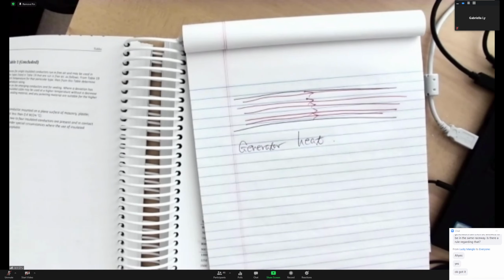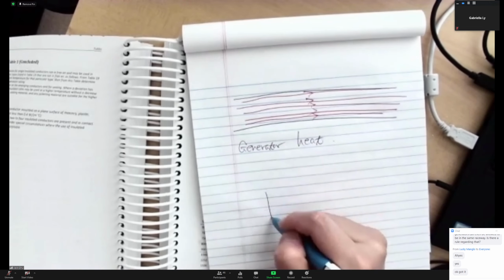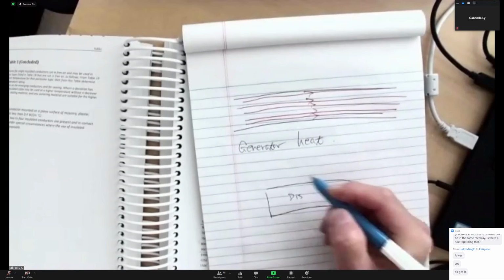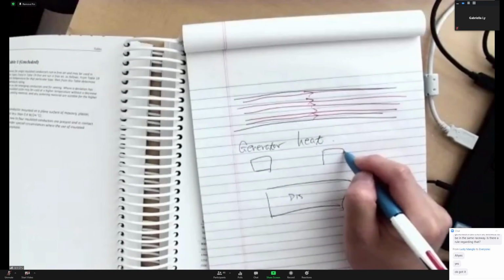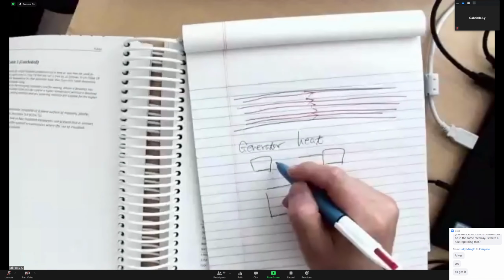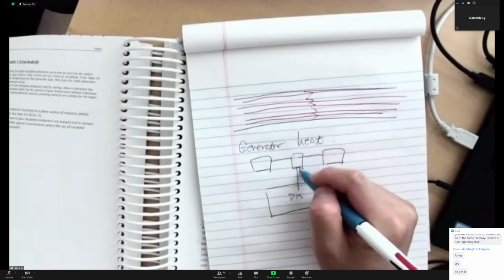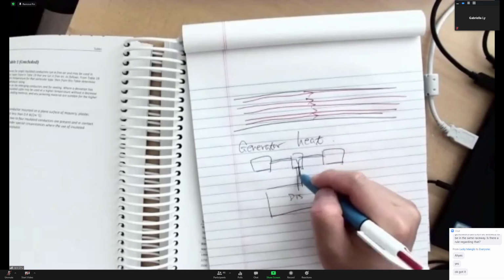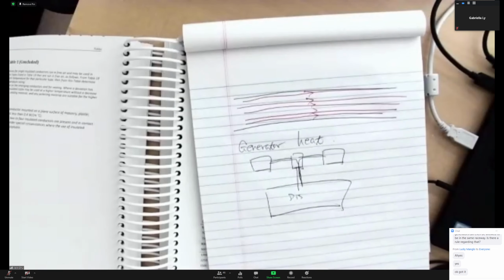Who said you cannot use... if you have your distribution panel, and you have generator 1 down here, generator 2 down there, then you bring them into a box. Those conductors cannot go into the same raceway. Yeah, divided by 0.8. That's why. The code only does not allow it if they are different voltage, right? If they are the same voltage, the conductors for sure can go through the same raceway.